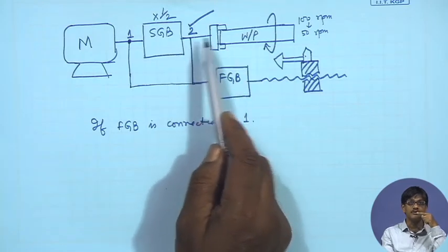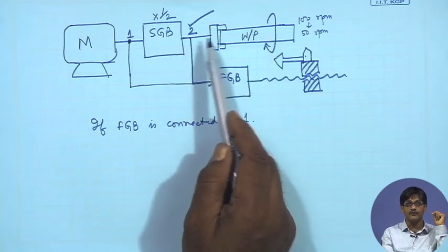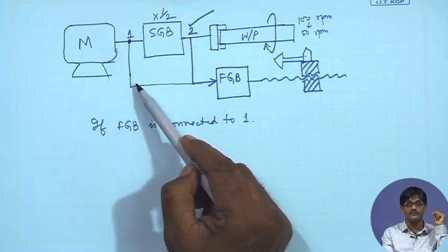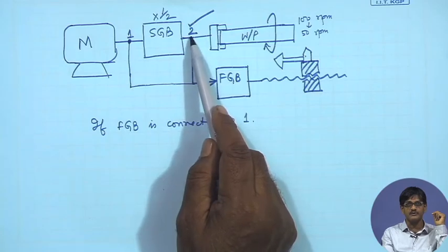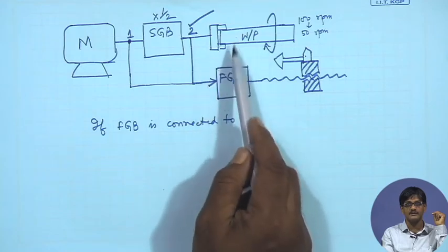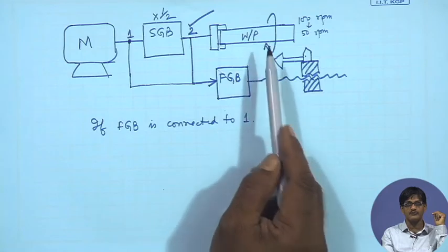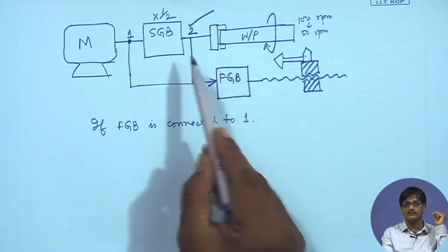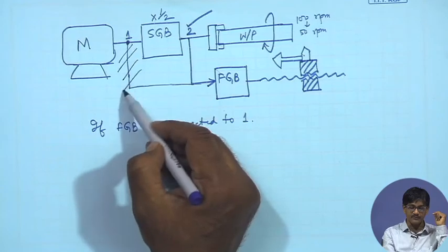You will say, I am simply changing the speed because I want to cut faster. No sir, if you make any changes here and you are having the tapping at the speed gearbox here, you are in trouble. So, by logic it has to be here, because whatever changes you are making here should be shared by this line also. Otherwise, their relationship will be disturbed. Wherever relational motion is important, you really cannot do this. So, that is why you have to be very alert.